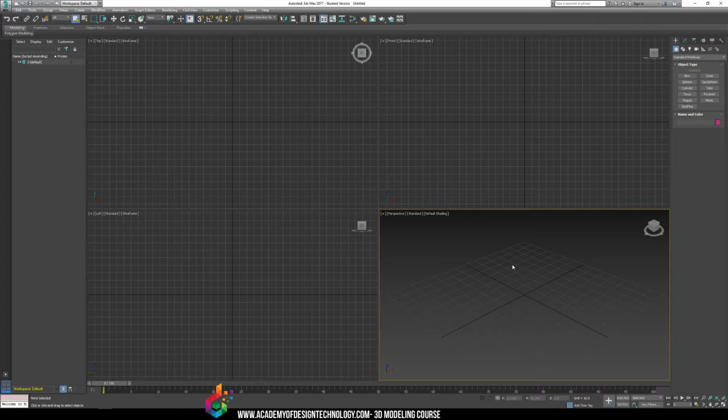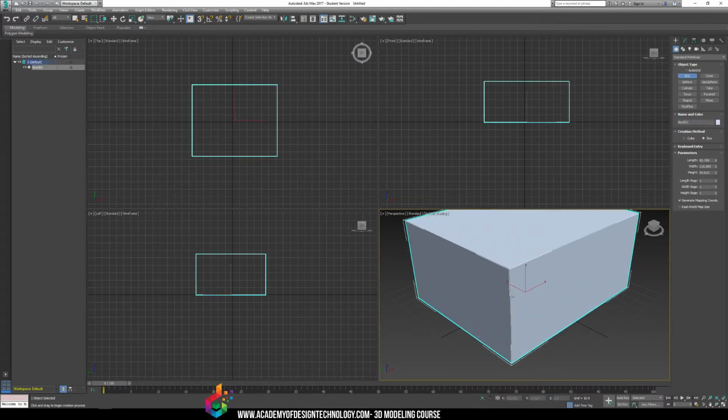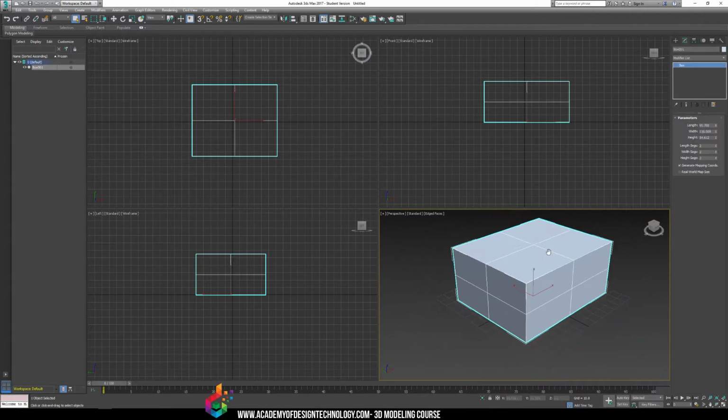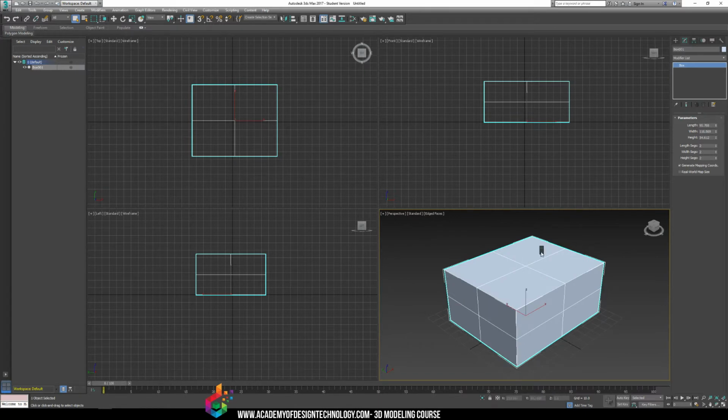The material editor is where we start loading in images inside 3D Studio Max and can assign different color polygons to a model we have, even if it's just a simple box shape or a cylinder, anything like that. We can start loading in materials. So I'd like you to create a simple box shape, and we're going to give it 2 length, 2 width, 2 height in the segments. And I'm going to right click on it and convert it to editable poly.